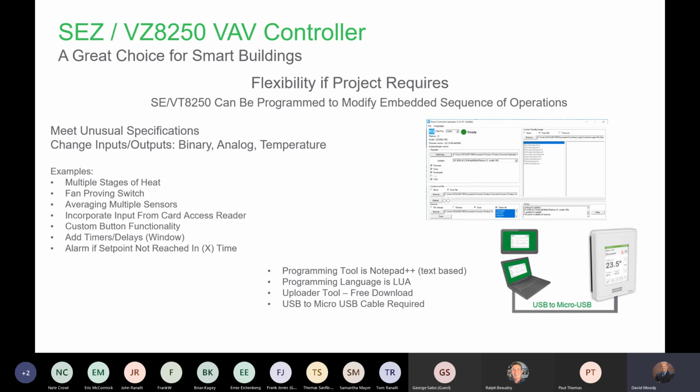But one of the other features that it has is it allows you to back up the configuration of a room controller. So if you've configured one, you want to plug into it and get its configuration out of it, you save it. And then if you want to go to another room controller and plug into it, you can take that saved configuration and upload it into the room controller and it will configure it. So you don't have to push all the buttons and configure every room controller. You just plug into it and it configures it and you walk away, right? That's what this tool does.